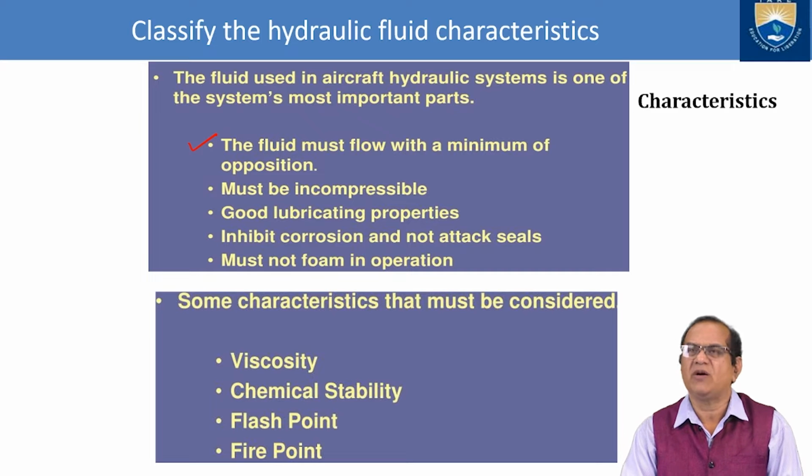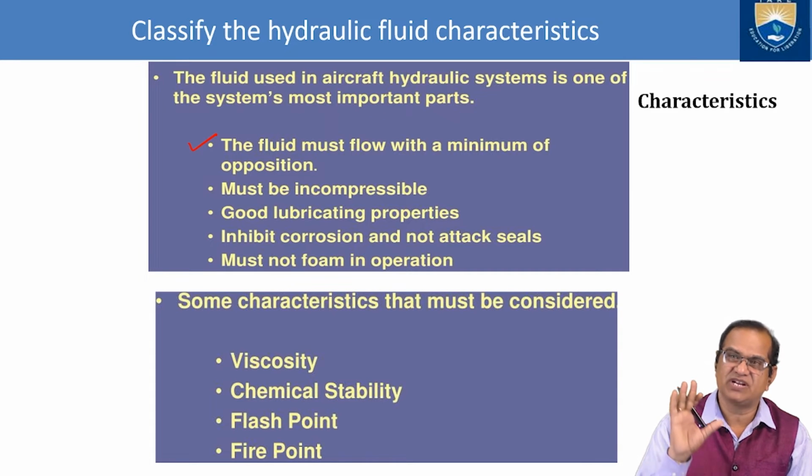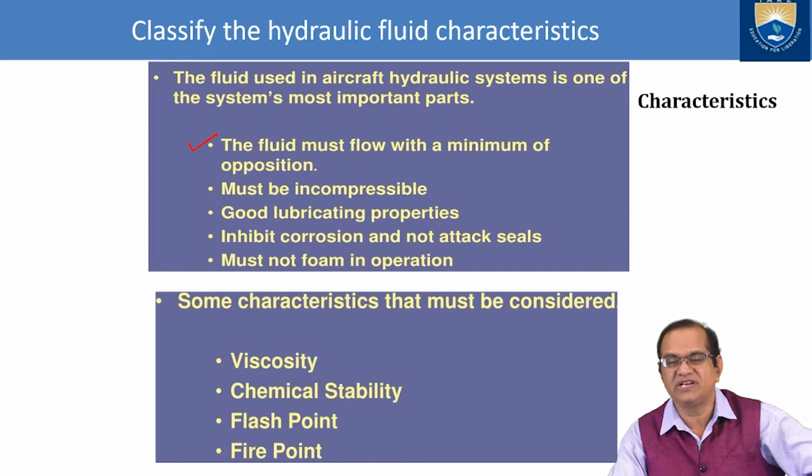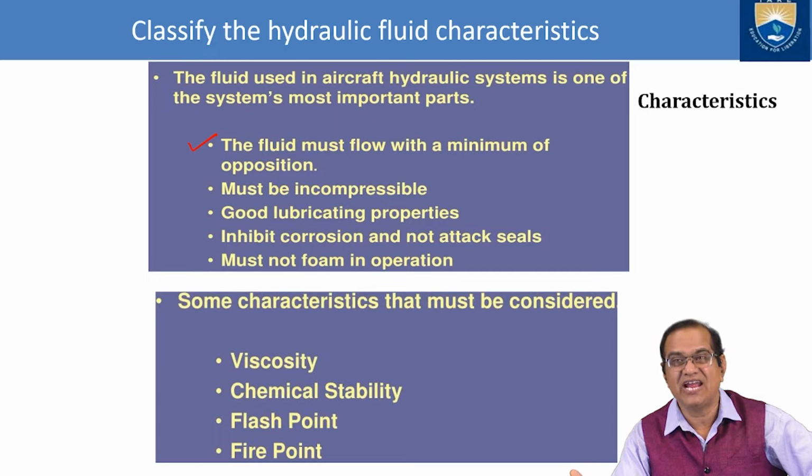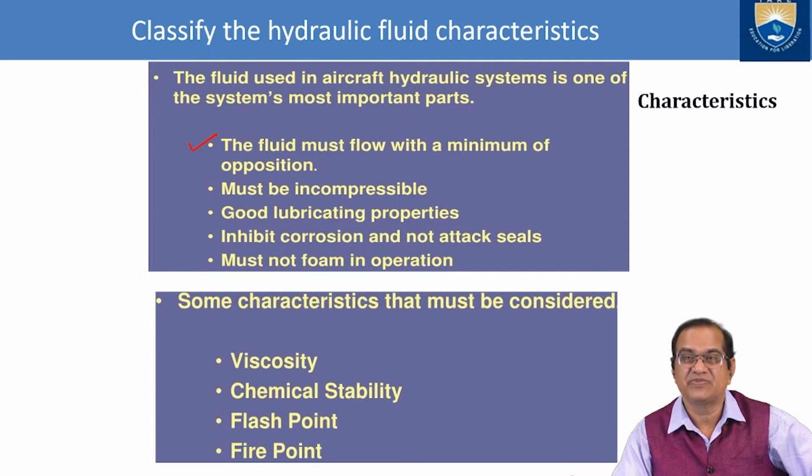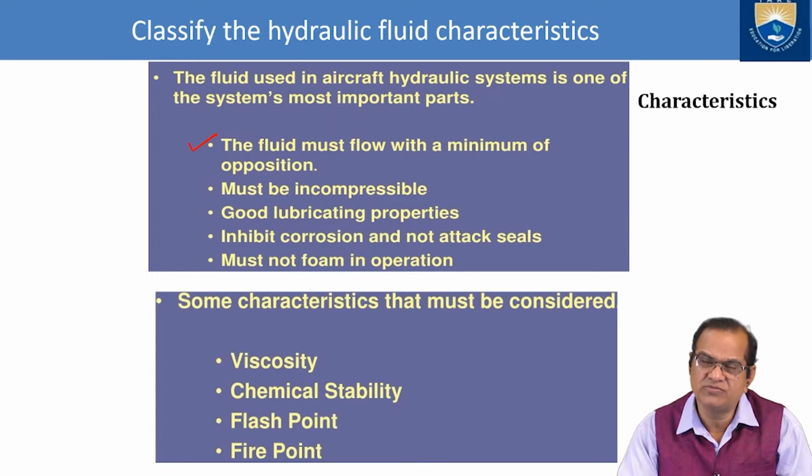Must not foam in operation. During high pressure, foam should not be generated, otherwise it will trap air, and this air is not good, and there will be a compressibility effect. So it should not form bubbles or foam at any operating pressure and temperature.